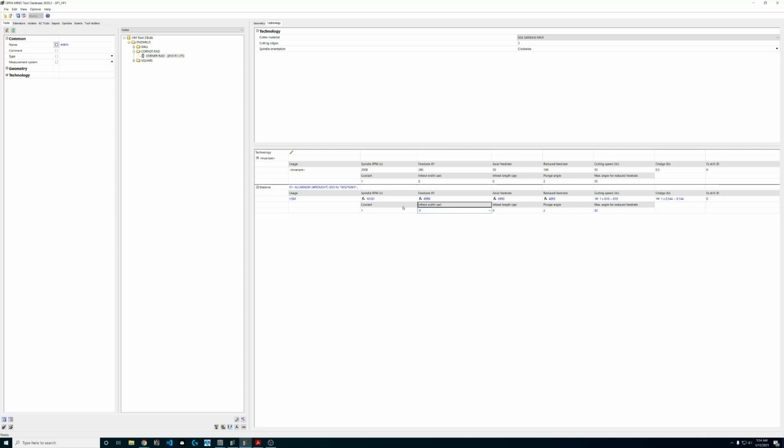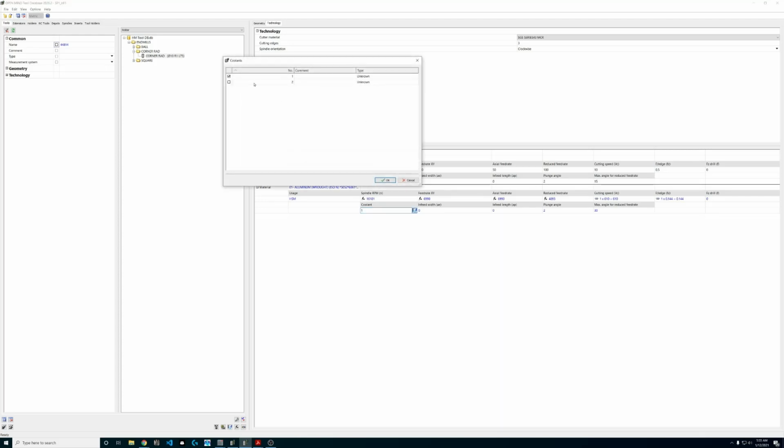So now every time you open up optimized roughing, as soon as you select a cutter, it's automatically selecting its infeed width and length off of the data driven by that cutter, right? I mean, you can even go so far as to define the amount of rest material to leave as a function of the step over or the cutter width of cut. You can do some really neat stuff, all driven from this data. So we'll take one step back here. Coolant, you're going to have defined some coolants.